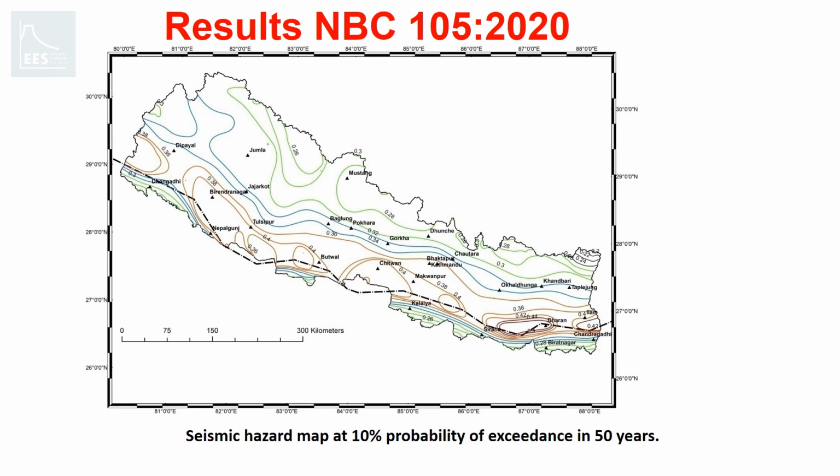Cities lying in this part experience more intensity, and as we move further up or down, the value decreases. Kathmandu has PGA of 0.35 G, while Himalayan regions such as Jumla have only 0.26 G. And you must also have noticed that the difference lies only in the pattern, not with the associated values. Yet surprisingly, the base shear coefficients obtained in the previous version were just too low, only 12% of the seismic weight if one was to design a moment resisting frame based hospital building in Kathmandu.